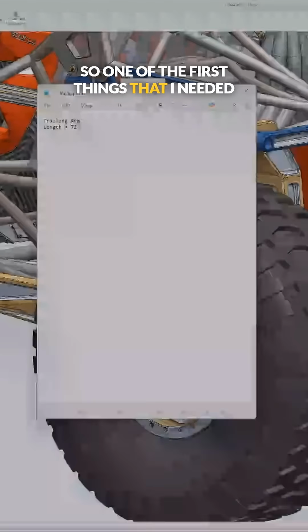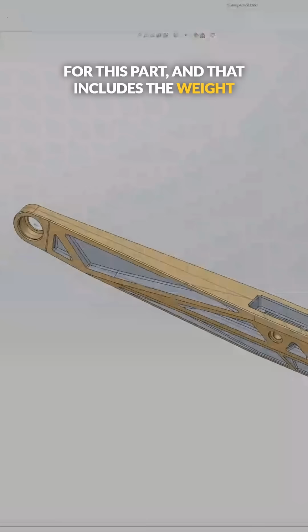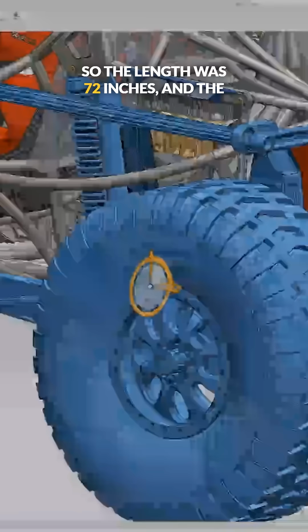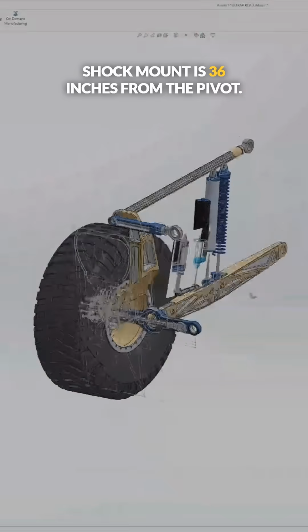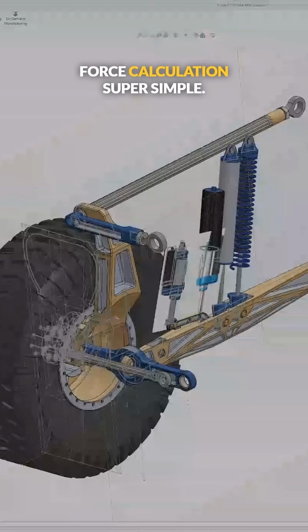So one of the first things that I needed to do is record the critical dimensions for this part, and that includes the weight and the total length and the shock mount. So the length was 72 inches and the shock mount is 36 inches from the pivot. So that dimension ratio makes the force calculation super simple.